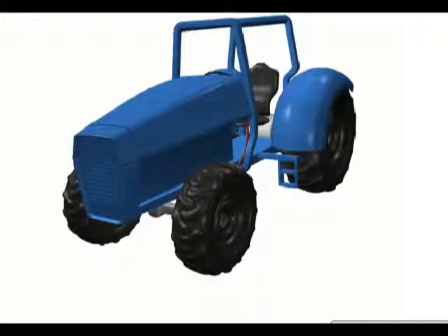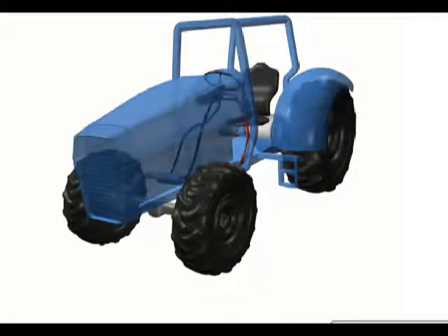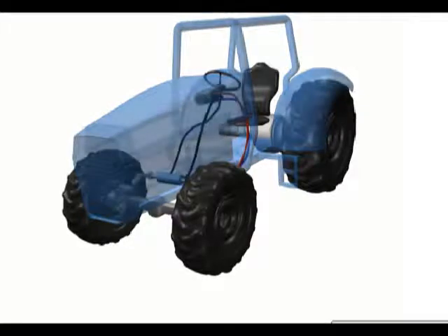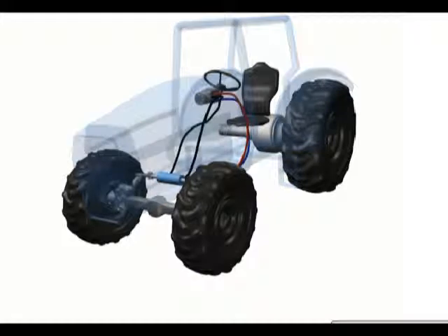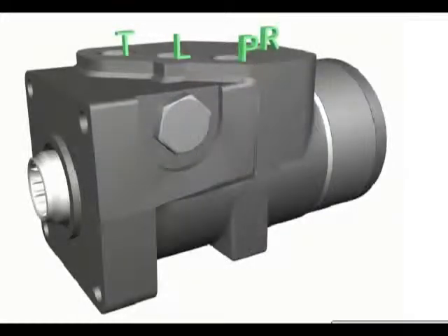Power steering units are used to assist in the steering of many types of mobile equipment. The power steering unit is a fixed displacement rotary metering valve which is activated when the steering wheel is turned. Most power steering units are gerotor or geroller design.